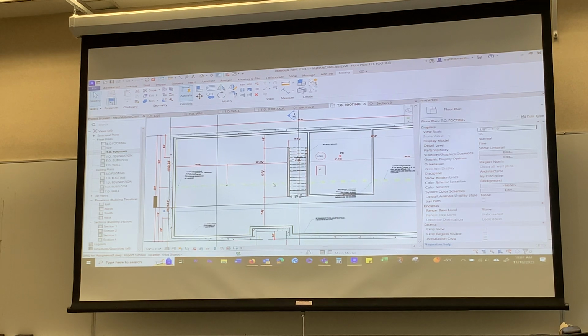That's fine, you can put it right. You're going perfect room style here. Well, I don't know, you've got to measure it. So you want to measure from the face of the floor to the nosing and see if you get 11 inches. But where's the face of your floor though, it's the gray thing, isn't it? Go to hidden line, you can't tell, and shade it. Light up your floor system. Okay, that looks like it's probably right, so just measure from there to the face of that thing, if it's 11 inches, you've got it. How about these?